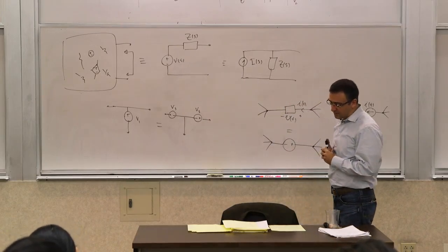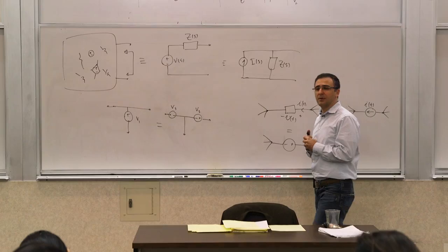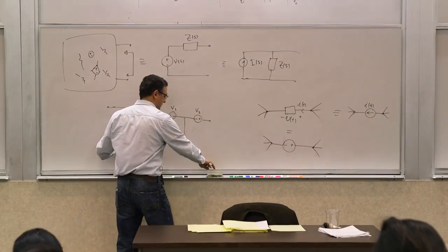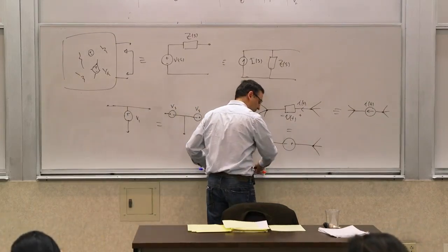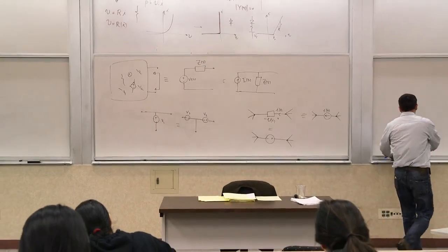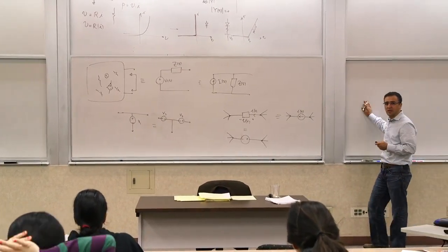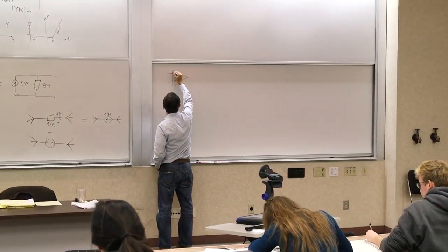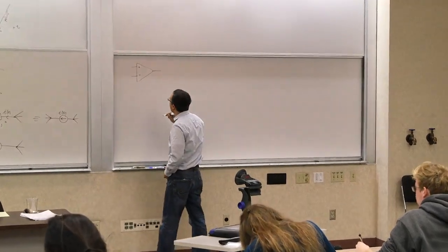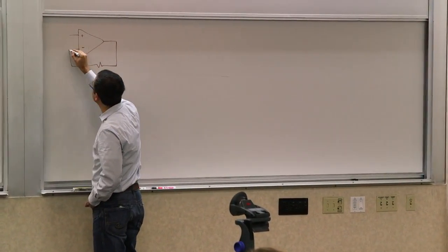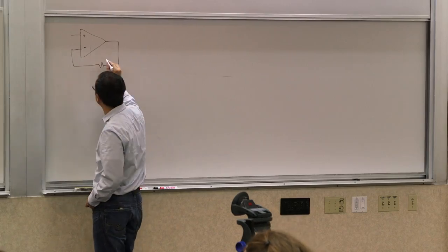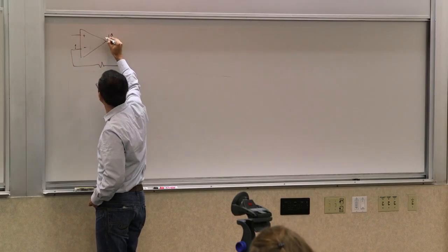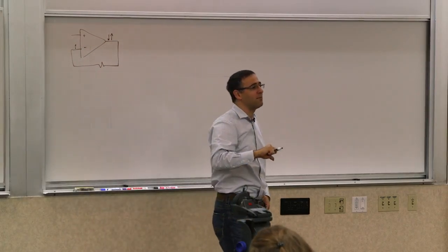Now, we also talked about active circuits in generality, particularly about op-amps. Let's go to a different whiteboard. If you have an op-amp, the model for this op-amp is an idealized voltage amplifier. One of the things that we saw is that if it is in negative feedback configuration, meaning that when one side goes up, the operation of the loop negates it, does the opposite.